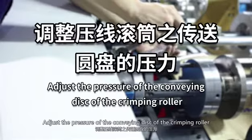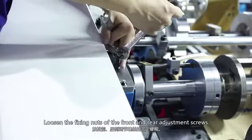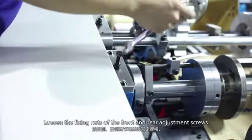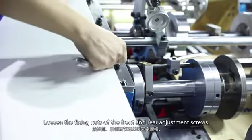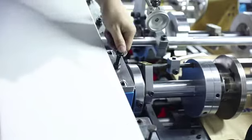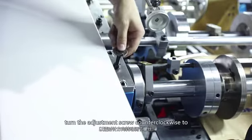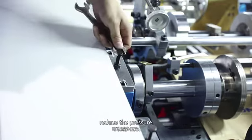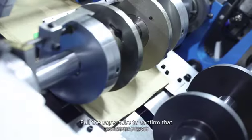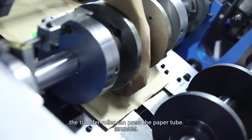Adjust the pressure of the conveying disc of the crimping roller. Loosen the fixing nuts of the front and rear adjustment screws. Turn the adjustment screw clockwise to increase the pressure. Turn the adjustment screw counterclockwise to reduce the pressure. Pull the paper tube to confirm that the transfer roller can press the paper tube.